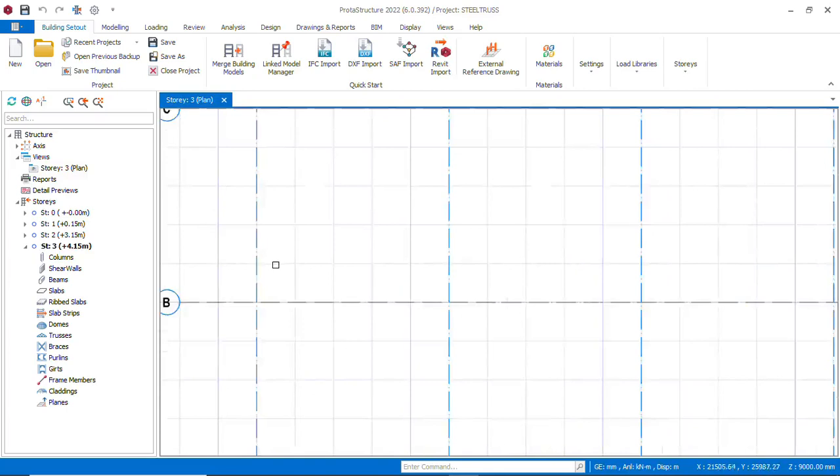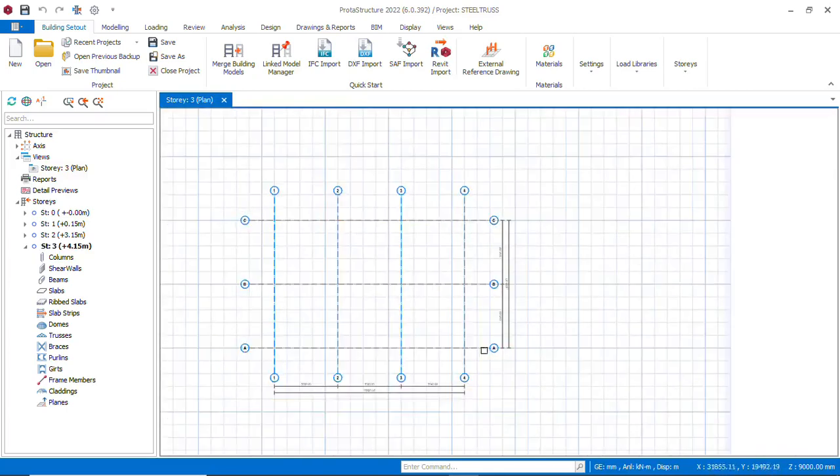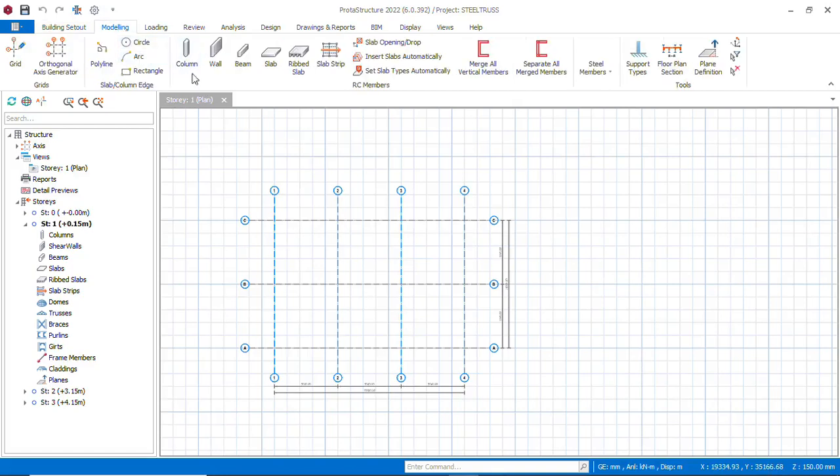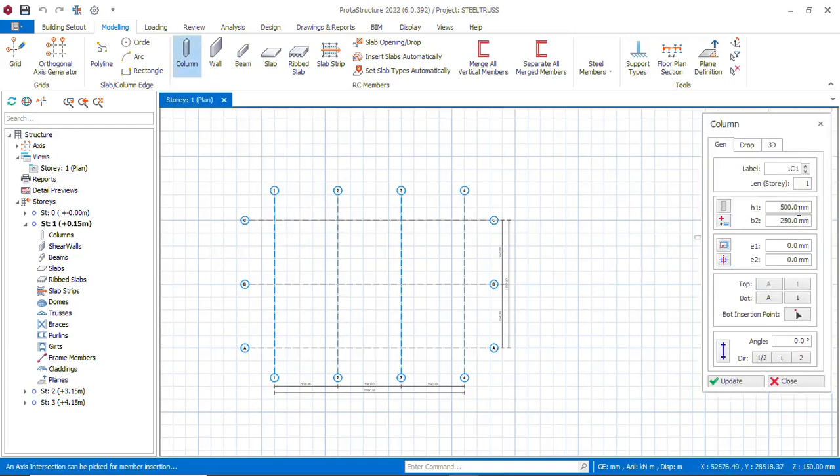Okay, so now we position our concrete columns. To do that, you can go to story 1 and go to modeling. When a story is highlighted, you see it's darker, it's thicker, showing that it is the current story. So you go to modeling, you go to concrete. A dialog box will come up. This gives the size of the concrete column we want to have here.